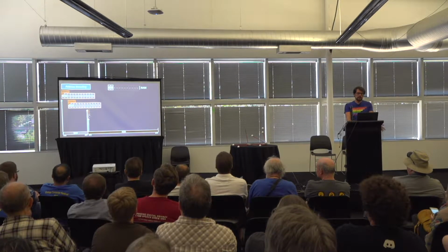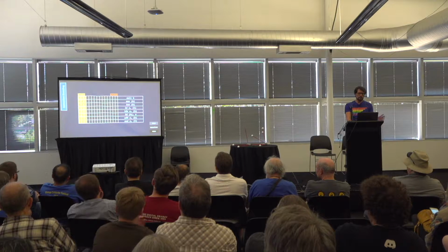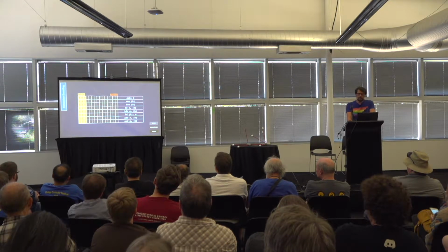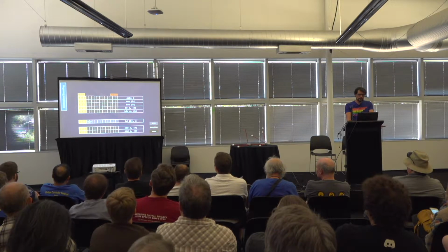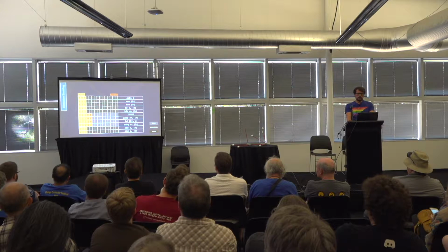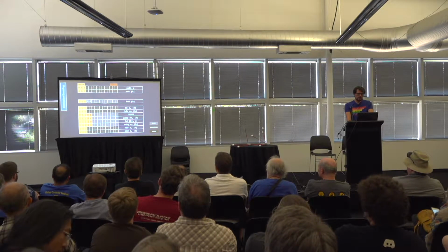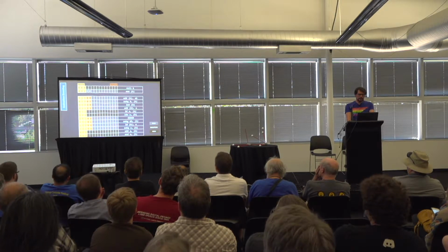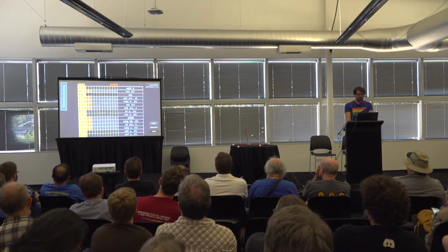RAM addresses always start with 00 as the uppermost 2 bits, and ROM addresses start with anything but 00, and this can be used in the encoding. So the store instruction, which only makes sense on RAM, only needs to encode 10 address bits instead of 12, which makes room for another 3 RAM-only instructions. The same is true for the increment instruction, which makes room for 3 more, as well as CCS, which shares an opcode with jump, which only works on ROM addresses.